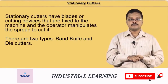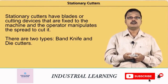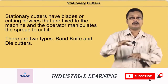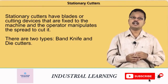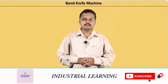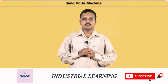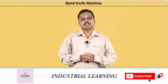Stationary cutters. Stationary cutters have blades or cutting devices that are fixed to the machine and the operator manipulates the spread to cut it. There are 2 types, band knife and die cutters. Band knife. Band knife machines have blades that rotate through a slot on the cutting table while cutting. The operator guides the fabric through either a push or a pull action towards the knife.